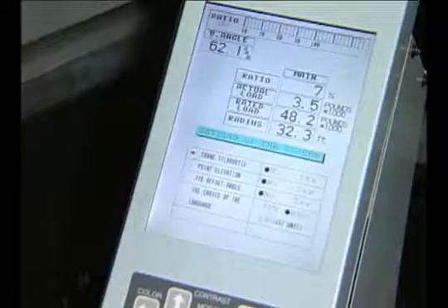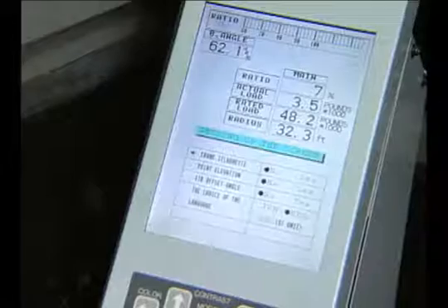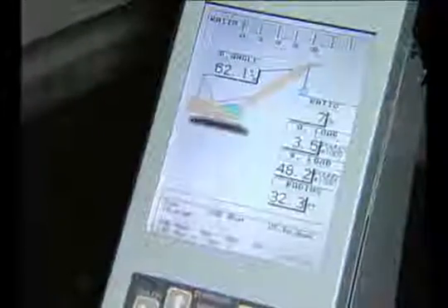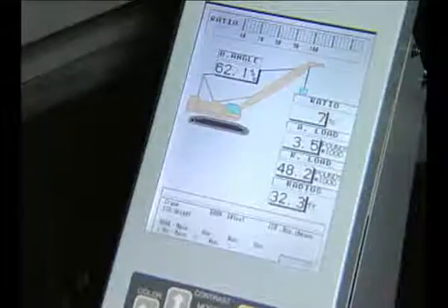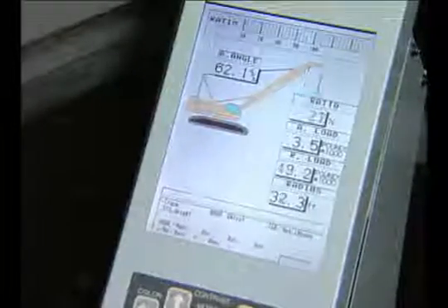In the setting of the screen mode, the operator can choose a crane silhouette on the main display screen. To demonstrate this, we will choose Yes and push Set. This gives a picture of the crane on the main display screen. In this screen, the operator must watch the load on the boom tip to shift when the mode button is pushed to indicate the use of main or auxiliary hook.